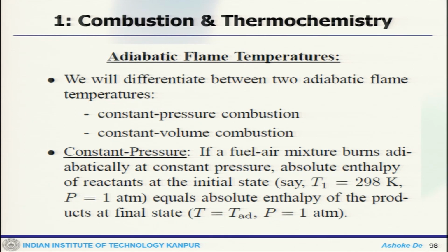Now, that brings us to another important parameter, which is the adiabatic flame temperature. This is again very specific to a particular fuel, and when it is reacted with an oxidizer or air. Even for example, when methane is reacted with air and when methane is reacted with oxygen, the temperature of the product would be different. Similarly, the adiabatic flame temperature would be different, but for a given fuel and condition, this is the theoretical temperature that can possibly happen.